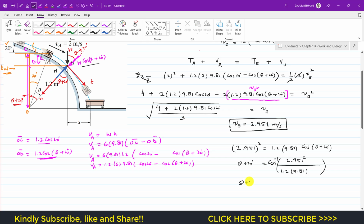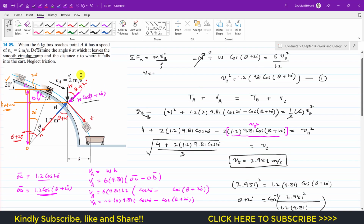So theta plus 20 degrees is 42.289 degrees, and now we can find theta. Theta is 42.289 minus 20 degrees, so this will be equal to 22.289 degrees. So this is that theta for which the box will lose contact with the circular ramp. Now after that, in the problem statement we were asked to determine the distance s that it will travel. So we have to find this distance s.